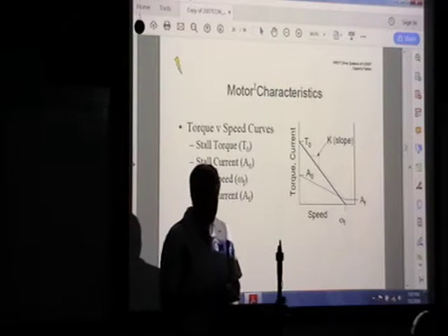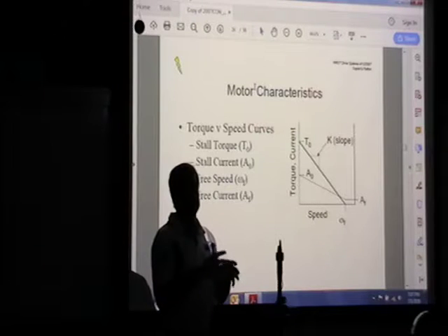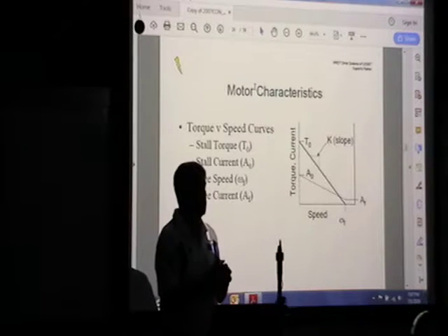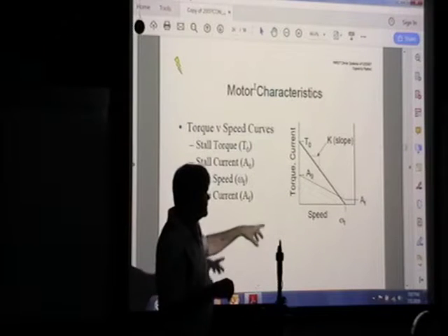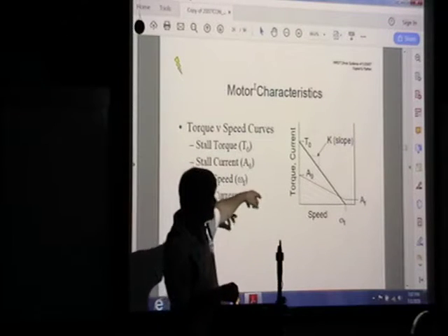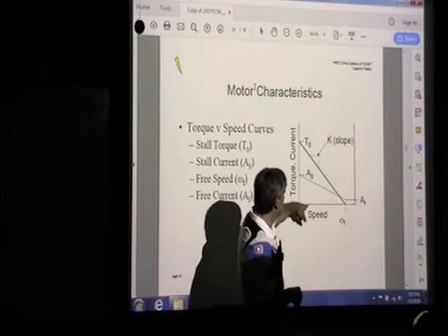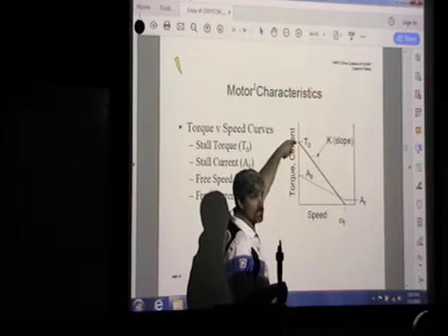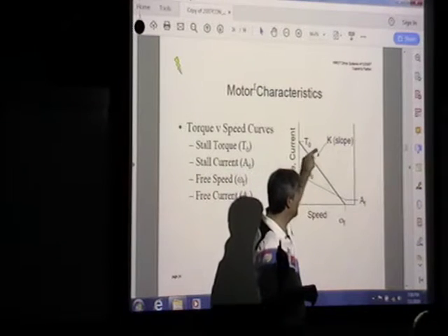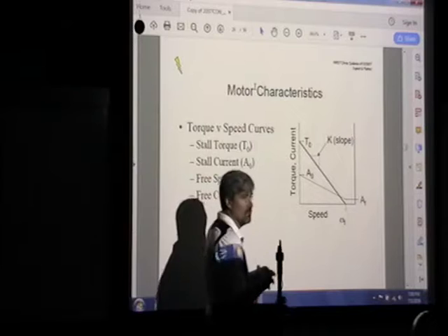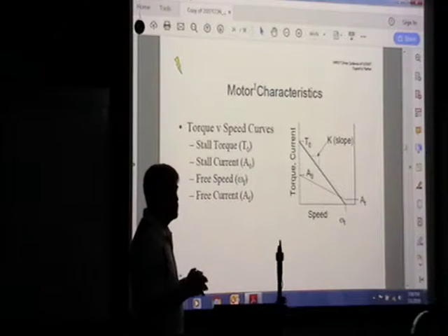Now these motors, when we talk about them, are variable. They don't always have a fixed torque, and they don't always have a fixed RPM. But instead, as you can see here, they've got torque, and this is the performance of the motor. At low speed, you've got high torque, but as your speed increases, your torque drops. And the slope of that line is different for each motor.